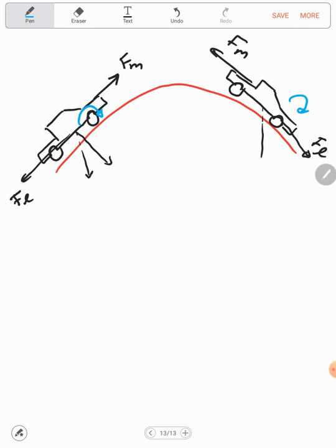So the regenerative braking is caused when the load torque causes the machine to rotate at a speed higher than the rated speed in the same direction of rotation. In this case, the machine will act as a generator, or it will enter regenerative braking. So here the machine is acting as a motor. Here the machine is acting as a generator.